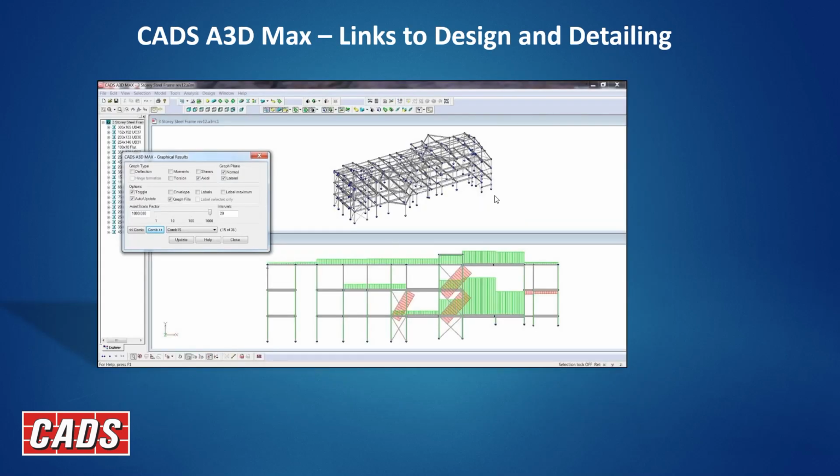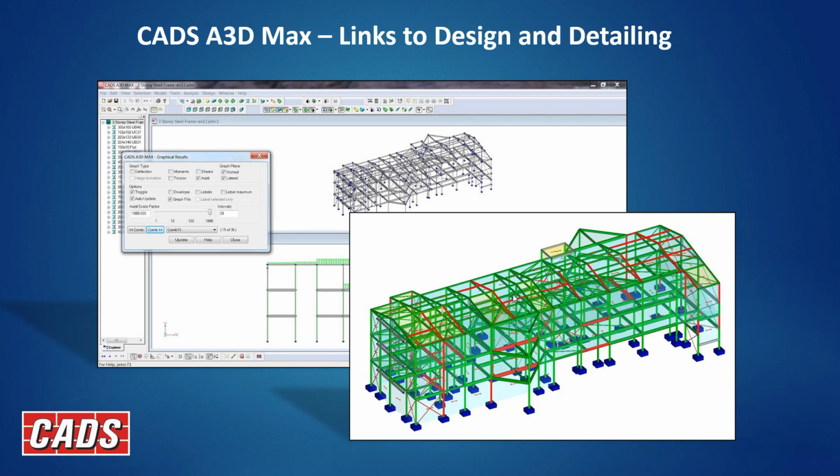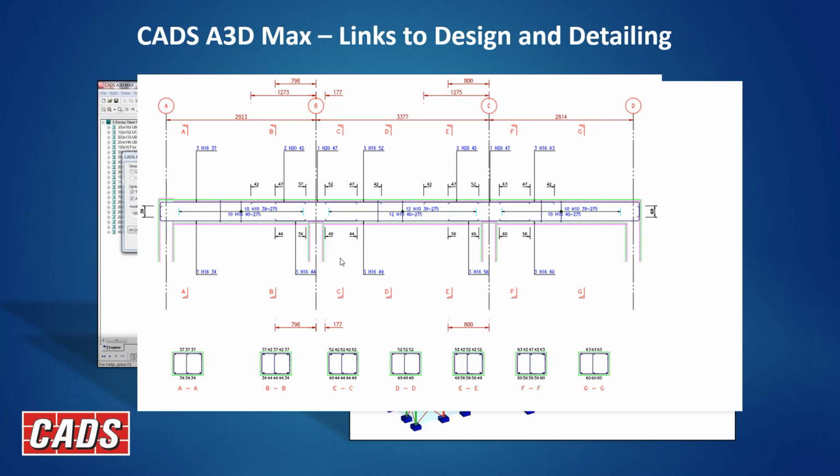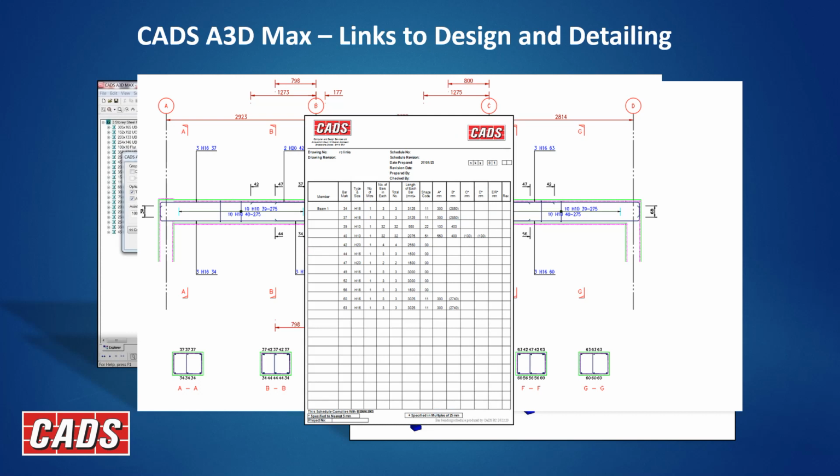Sort of images of the work we did in this session. I showed you the typical way to produce annotation of internal forces, including deflections, moments, shears, the labeling of such. And we looked at the design. So this is showing the green and the red pass and fail annotation for design checks of the steel frame. I then showed you DXF for doing layout drawings, automatically created from the program. And then CAD's RC Beam Designer for the annotation of the continuous beams. And also it could be pile caps, pad bases, columns, and scheduling.